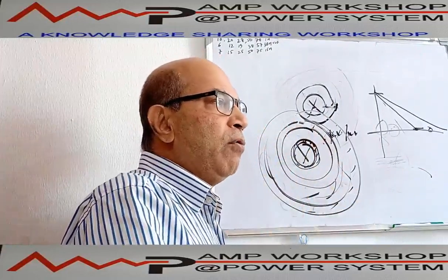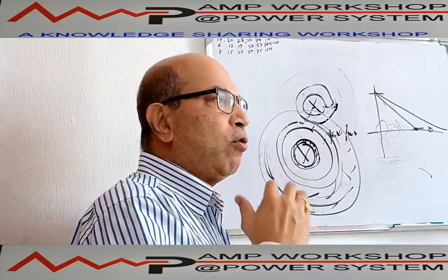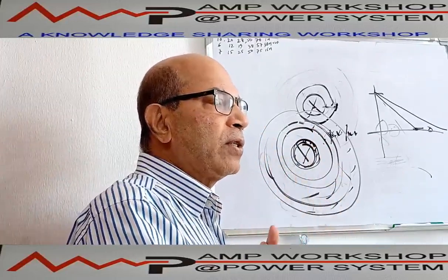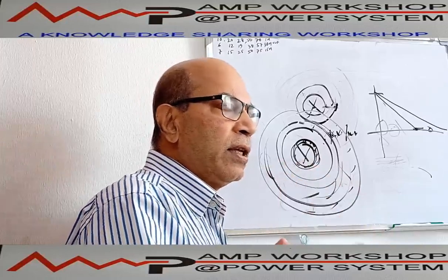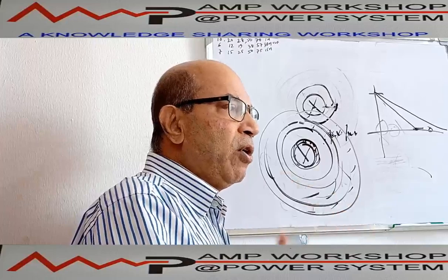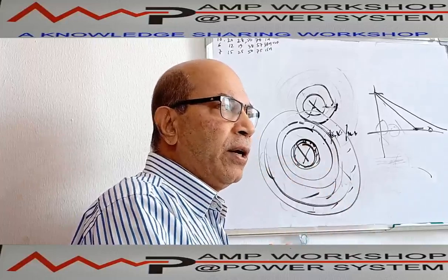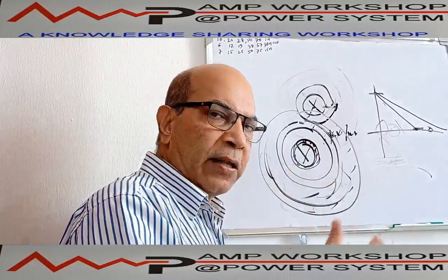In brief, we can say a cable has a conductor, and over the conductor, for the medium and high voltage cable, there is a semiconducting layer. Then the insulation will come. Over the insulation there is a semiconducting layer. Over the semiconducting layer there may be a water barrier tape. Over that it may be metallic. Then there will be metallic tape.